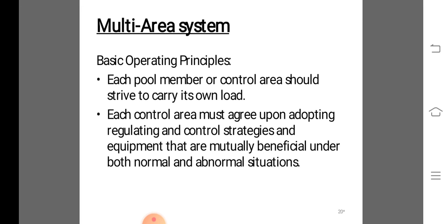Then it has been shown that the load frequency control system possesses an inherent steady state error for a step input. Applying the usual procedure, the dynamic response of the control loop can be evaluated, so that the initial response can also be seen for any overshoot.